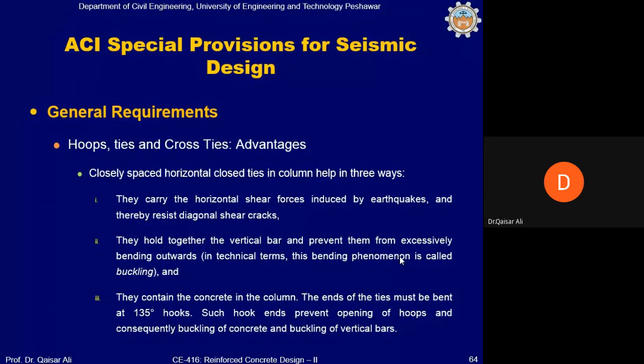Then the bond between steel and concrete will no more exist, and in this situation, the steel will be alone against the gravity load. So under this situation, the buckling of steel can occur. But if closed ties have been provided all around these bars, then they will prevent such type of buckling at the collapse stage.